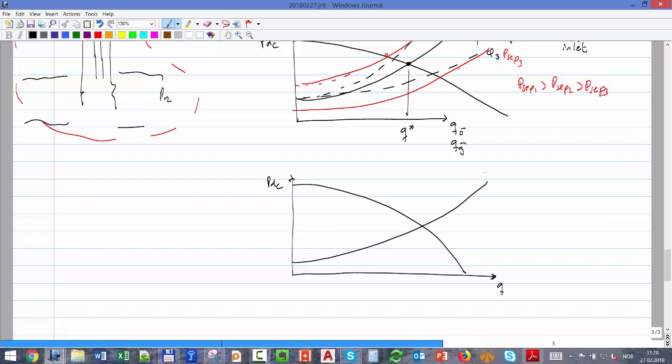Okay, so remember, what was the effect of the choke? This is 100% opening, 80% opening. Then you had 50%, for example, 20%. So that's how you reduce the rate. Just by changing the choke, that's going to change your available pressure curve, and that's going to move the intersection of the system. Okay, that clear? Yeah.